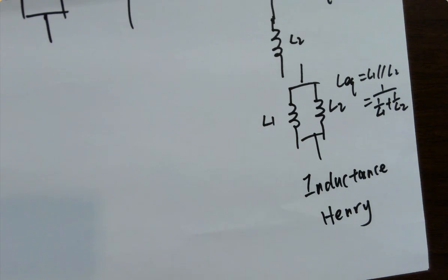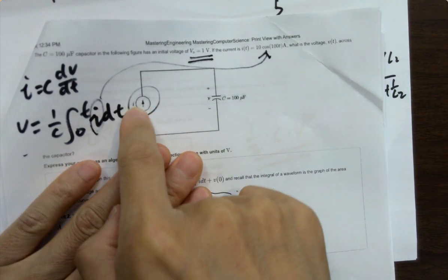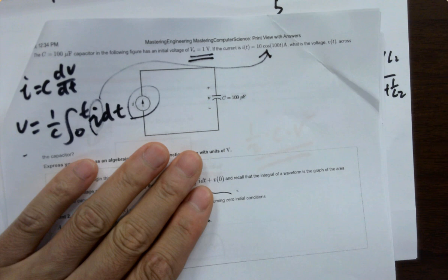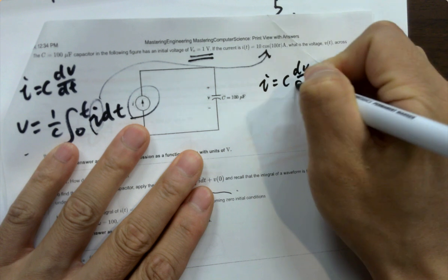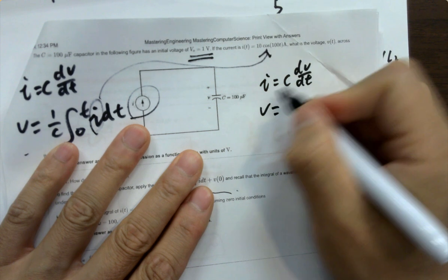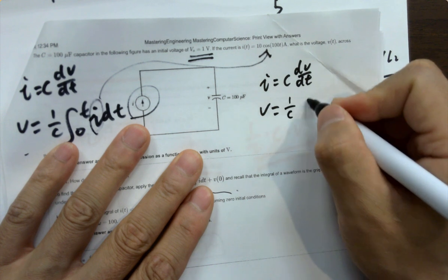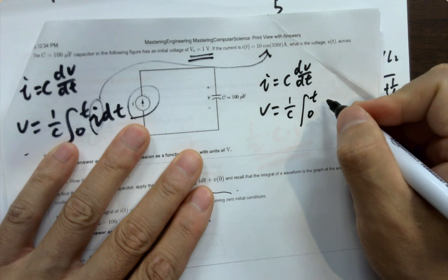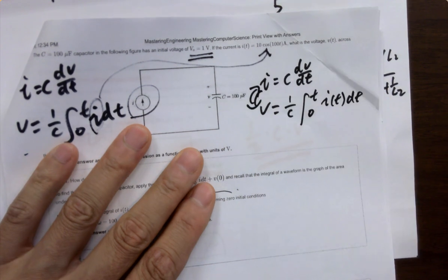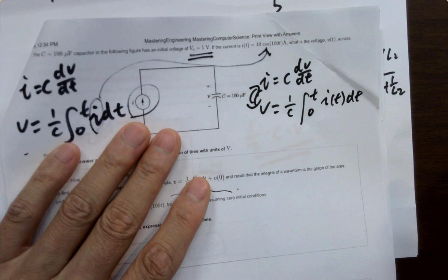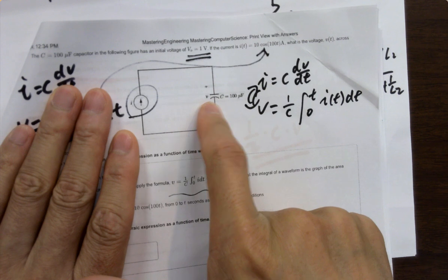And another problem you'll see here, it's not using a voltage anymore, it's using a current, directly dumping current into it, which is fine because if you know that I = C dV/dt, you'll know V equals, just calculating in reverse, backwards, 1 over C and integrate from 0 to T for I, right? It's basically the same stuff. Okay? So if you're directly dumping current to the cap, you could do it, right?